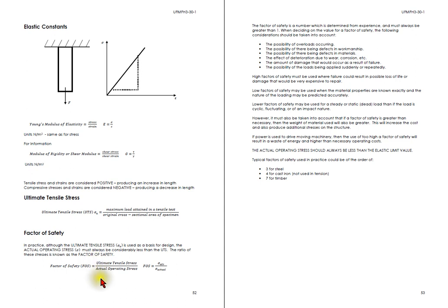Factor of safety is measured as the ultimate tensile stress divided by the amount of applied stress that you're planning to apply. Basically we're working out the maximum stress that you can apply. It's a bit like when you're going to buy some flu medicine and ask what's the maximum I can take, and we're going to take slightly less than that, and that will be the applied stress. So a big number divided by a number not so big, maybe halfway up, and we end up with numbers like 2 for the factor of safety. So 1 divided by a half will give me 2.